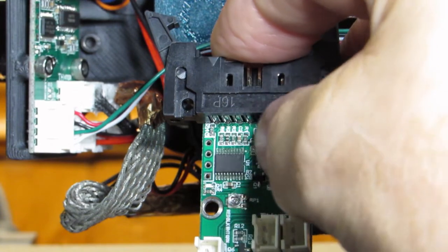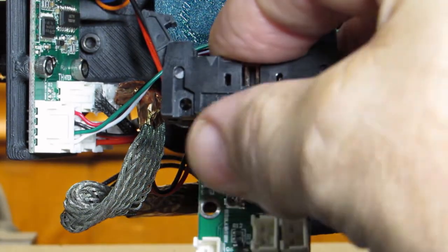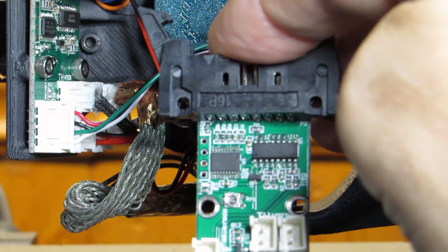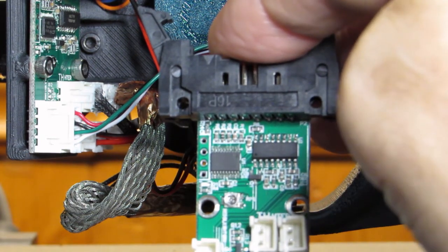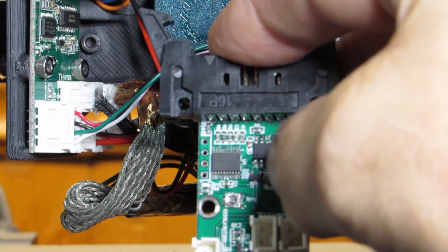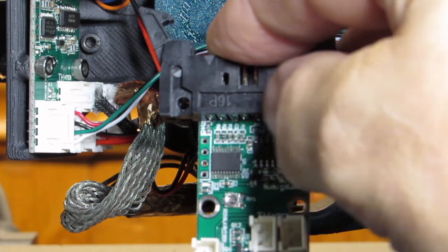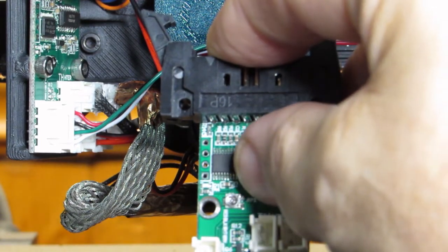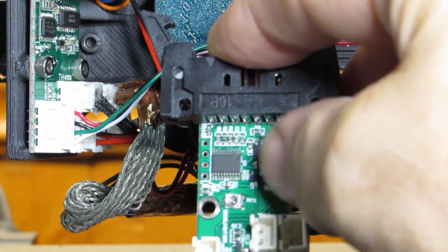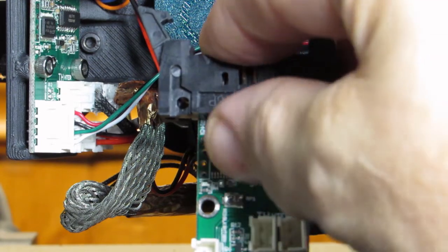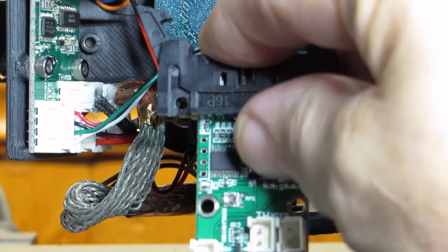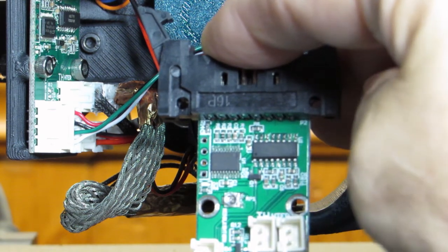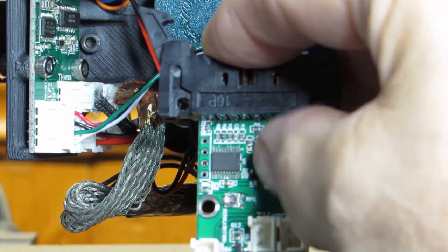The other chip, the small one you can see now, is an STM32, much like the one on your motherboard. It's programmed to look at a value with an ADC, an analog to digital conversion function built into that chip, wired to the output of this potentiometer. It's really hard to see with the big fat thumb there, but just to the right of the screw hole, there's a screw, you see? That's the top of a potentiometer. It's labeled RP1 on the daughter board.